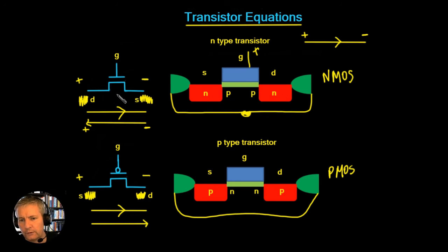Now what we would do, we would take this drawing here, and you could put a fourth point here in that drawing, and we could take it along here and just connect it to that point there. And we could say that this here is now the new symbol for this device. But generally we don't need to do that, because it is understood that the bulk is connected to the source, so we can just leave it like this.